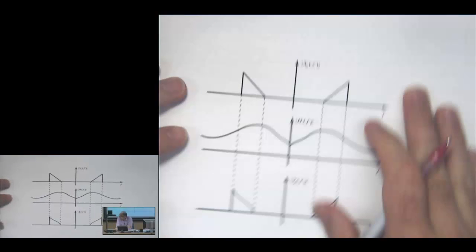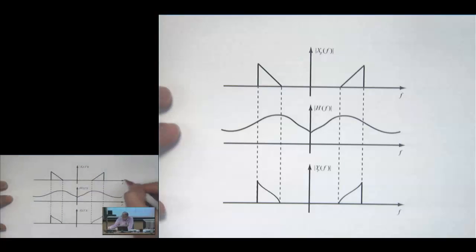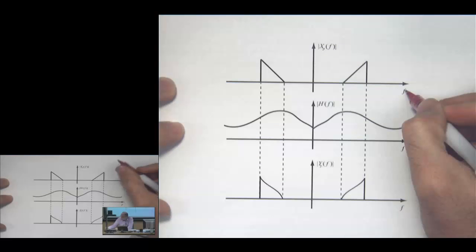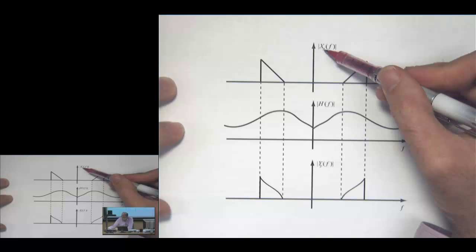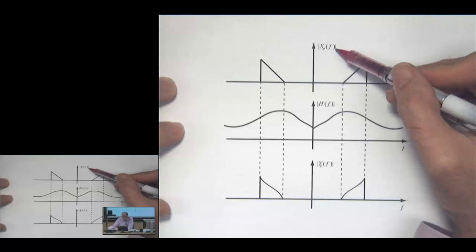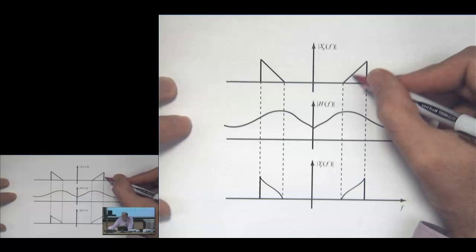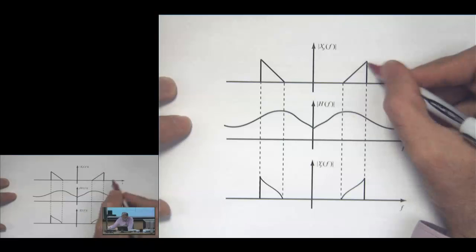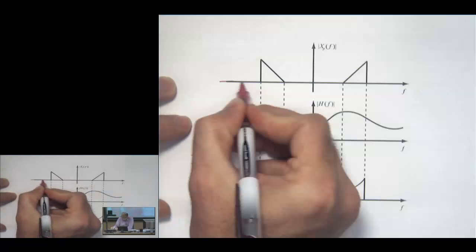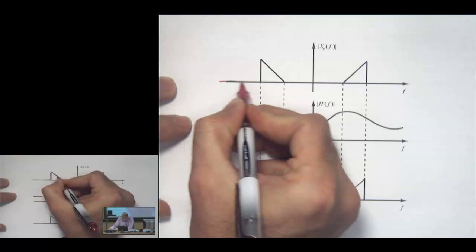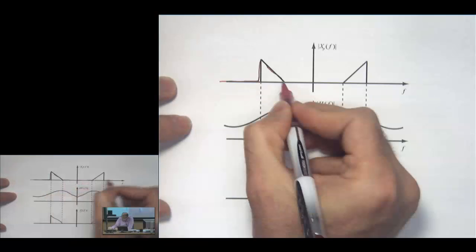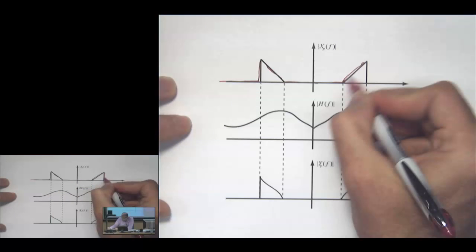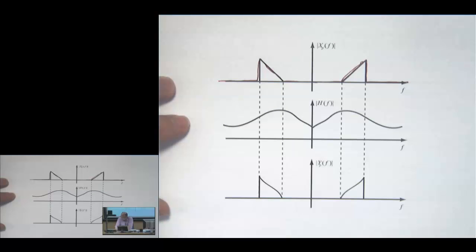So this is effectively what we want to do here. It's a spectrum plot. This is frequency. This is our passband X signal in frequency. And remember, this is just an example. Not all signals look like triangles. This is going to be some spectrum, and the point is that it's 0 signal here. And of course, we expect signal on both sides because of conjugate symmetry. The signal is real.